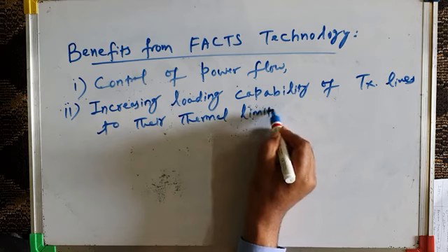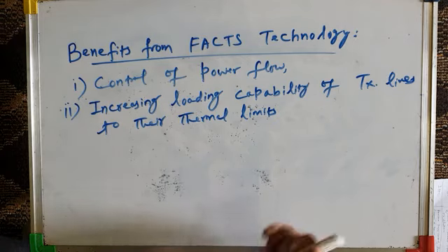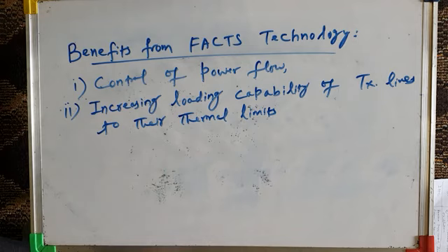As you already know, AC power transmission lines cannot be loaded up to their thermal limits because of stability issues, which we have discussed in detail in HVDC power transmission systems, which was one of the courses in our MTech second semester, last semester, spring 2021. Now, the maximum power angle that you can have is 20 to 25 degrees, whereas maximum power transfer capability takes place at delta equal to 90 degrees, but you can never operate a transmission system at delta equal to 90 degrees due to stability issues.